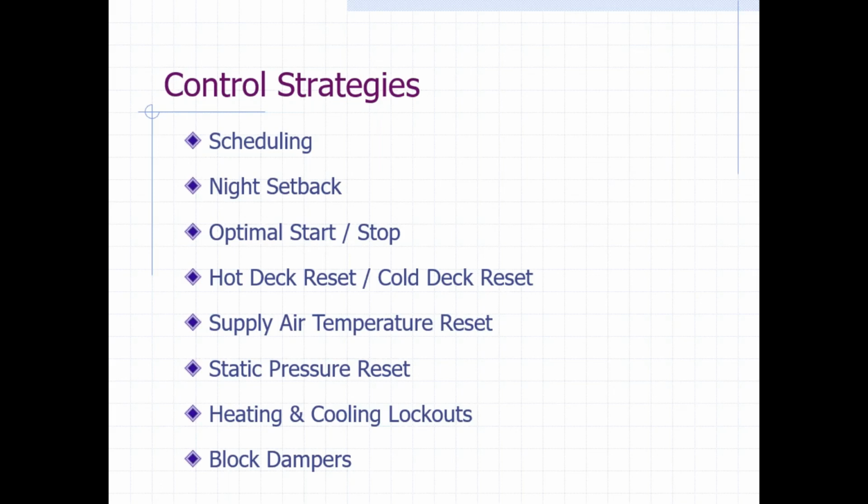So that's another thing. If you have a dual duct system, you might just say, well, how about this? If it's warmer than 70 degrees outside, just turn off the whole boiler. We don't need any boilers. We don't need any hot water. Forget it. And then the hot deck will just be the return air temperature, whatever is the return from the zone, and then the cold deck will be 55, and then we'll just deal with it that way. So that's what a heating lockout is.